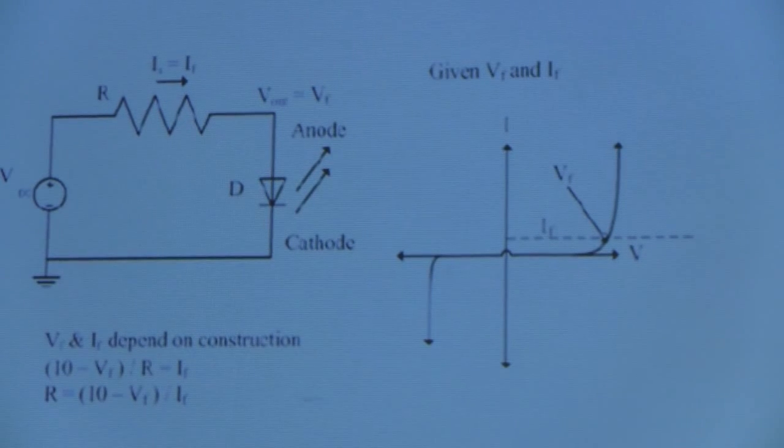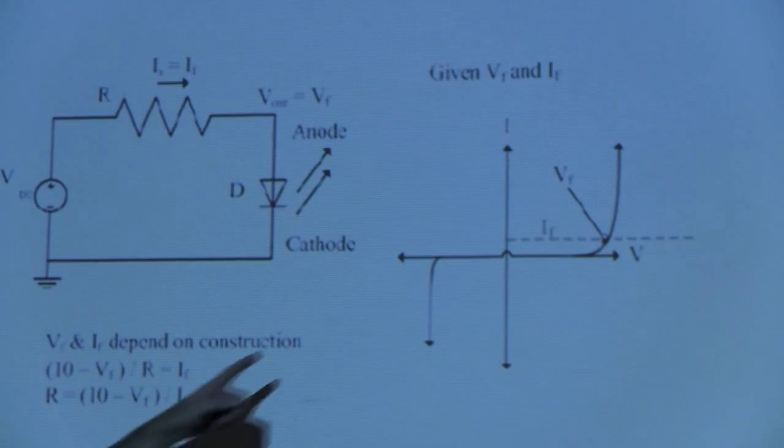Related to that, I just wanted to point out one other factor with an LED that can nail you, and that is, like with rectifiers or high voltage Zeners, hooking your 10-volt power supply backwards may be harmless. With LEDs, quite often the maximum safe reverse voltage is relatively low. Yeah, so just talking about this value right here.